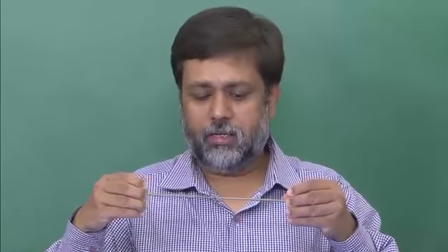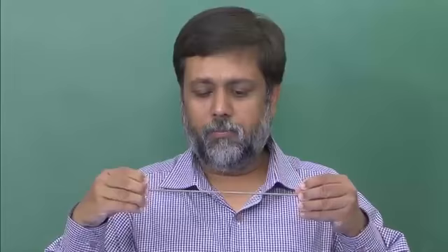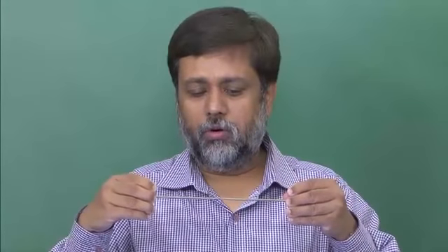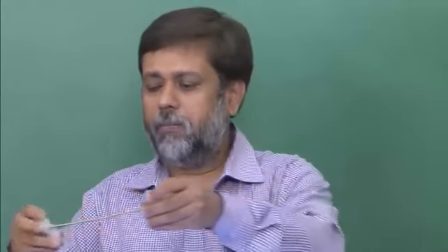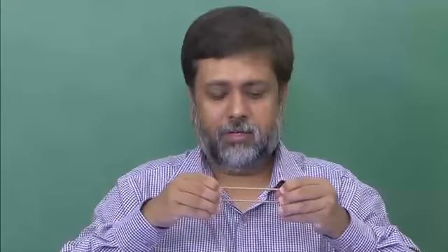It is not shared. Now you can see that this system is more flexible, so no wonder that the transverse modulus is much smaller in comparison to the earlier system, which has the same type of spring stiffness but is much stiffer.